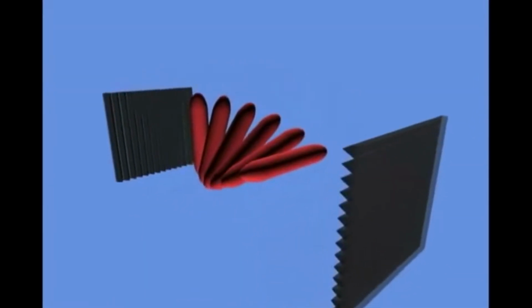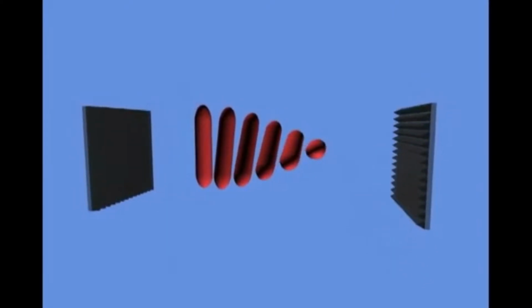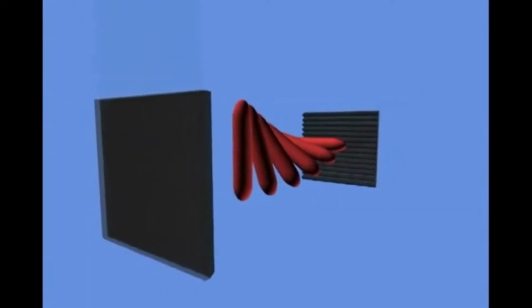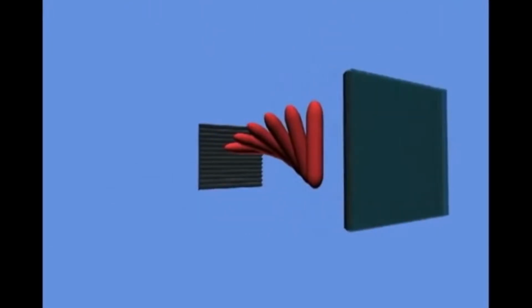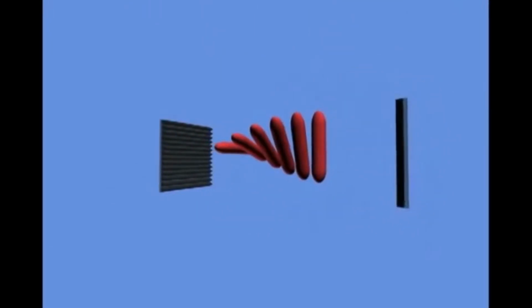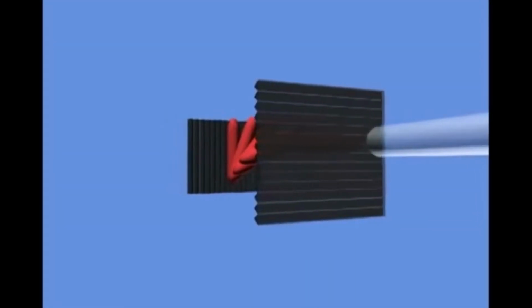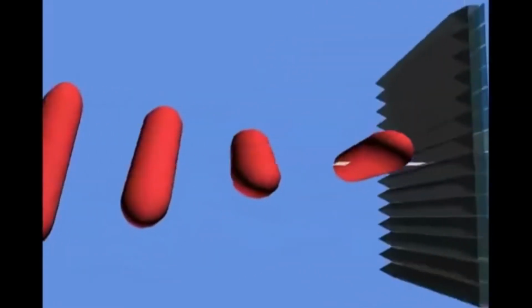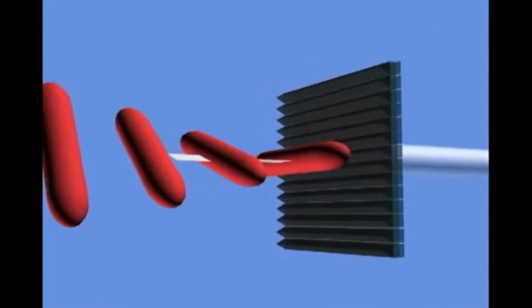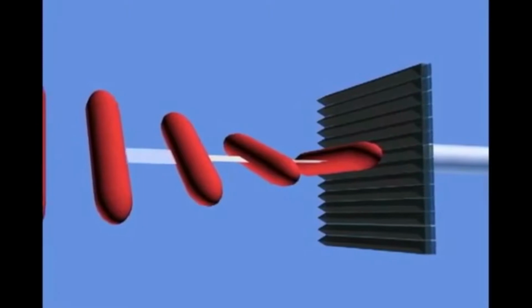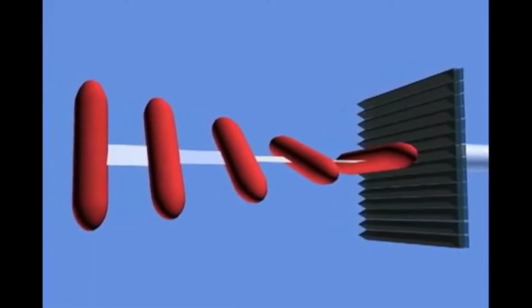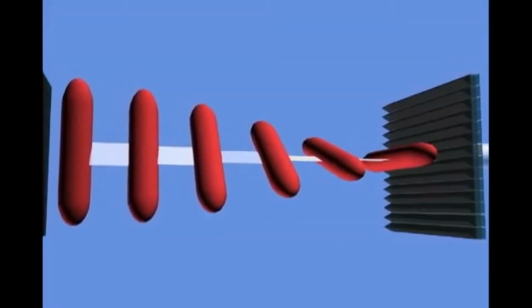A polarization filter is fitted onto each of the outer glass plates. These polarization filters mean that only one dispersion direction of multiple light waves emanating from a light source is allowed to pass through. The light follows the rotation of the molecules and, twisted by 90 degrees, hits the outer polarization filter. As the rotation means that the direction of the light matches that of the polarization filter, the light can also pass through this filter and brightens the outer glass plate at that point.